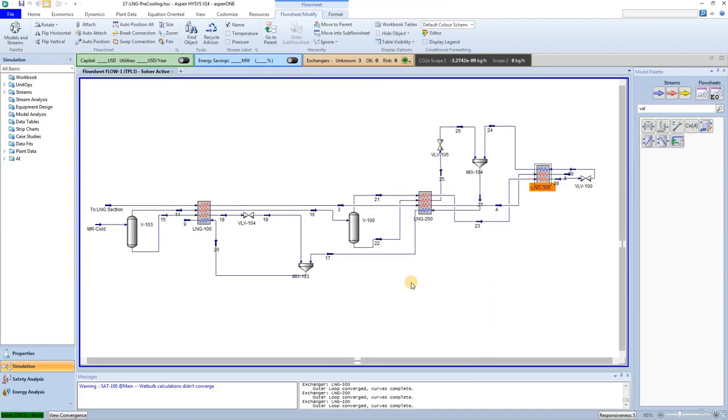The three LNG heat exchangers and the subflow sheet have calculated at this point. The last step is to drop the pressure of the LNG stream and separate out the desired liquid product. You will add a valve operation followed by a regular separator to achieve the final product. Add the final valve and separator.